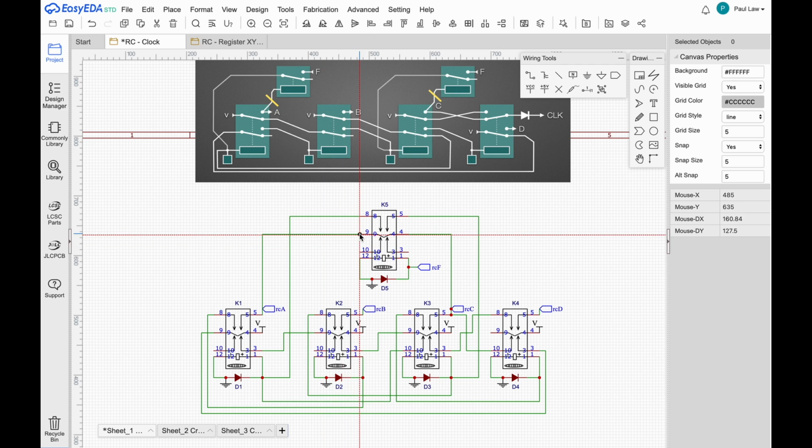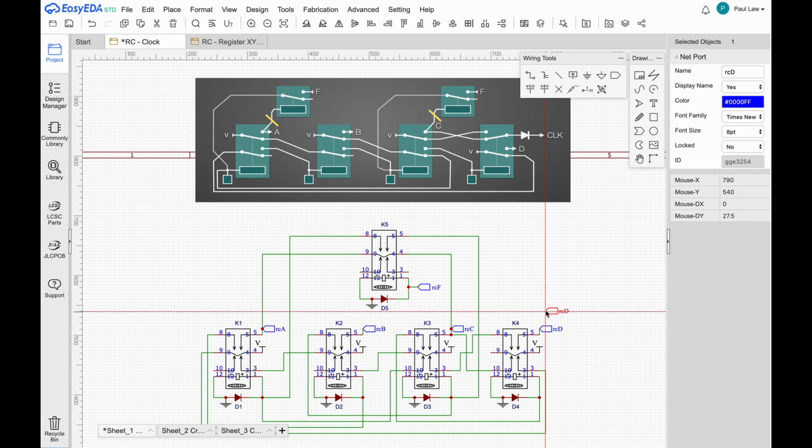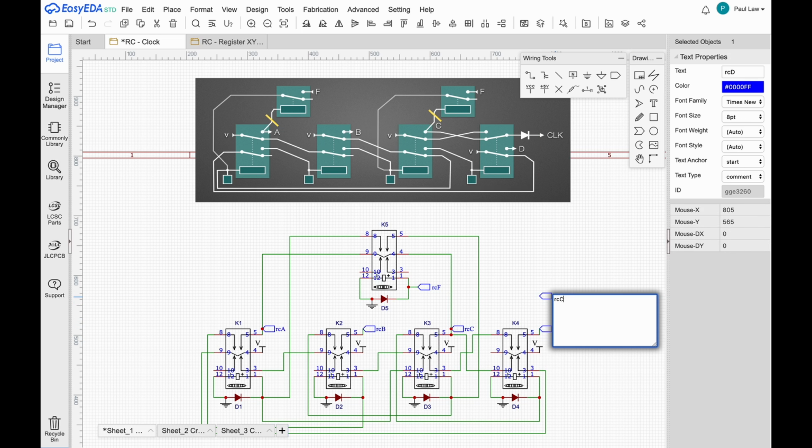This would mean that stage A locks on if the freeze line is set and we're in state A, or alternatively if we're in stage C and the freeze line is set. In other words, if we're in stage B or D, it will run through to the next stage regardless of the freeze line state. This optimisation was spotted by Carl Anderson, who posted in the comments of episode 8. So thank you, Carl.